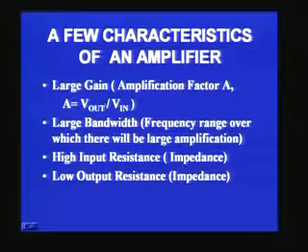The other thing that we worry about in an amplifier, briefly, is large bandwidth. What do you mean by bandwidth? An amplifier will amplify audio signal. For example, in an audio amplifier that we are all familiar with in a public address system, if I speak at the microphone, I must get a very loud, magnified sound through a loudspeaker. But my speech will not contain one single sine wave because it is composed of several sine waves. The signal will be a complex signal which is a superposition of several sine waves, and therefore my amplifier should be able to faithfully amplify all the different frequencies contained in the input signal. For example, if it is music or an orchestra, you have different instruments generating signals at different frequencies. All of them should be faithfully magnified and given at the output through the loudspeaker, then only would you get good music coming out of the amplifier.